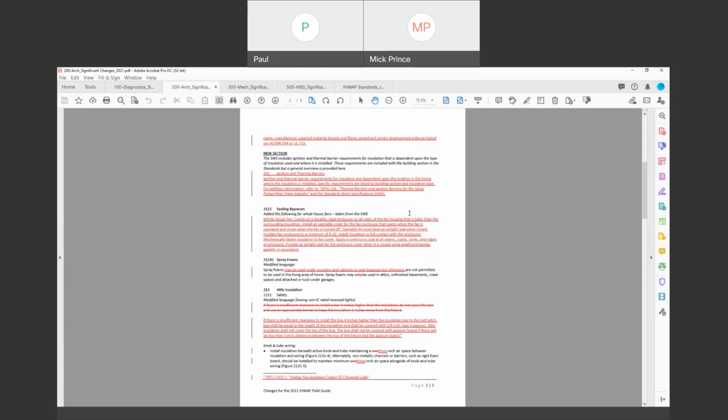Hey, Paul, why is the rim joist excluded from this? The code says you can get up to 3 inches of spray foam before it has to be covered with an ignition barrier. Okay. So in most cases, we're not going more than 2 inches, so that can definitely be exposed. And that's in a rim joist only, where you can have up to 3 inches. Yes, rim joist, basement or crawl space. That's correct. It's basically a de minimis area and thickness. Yeah. Right. Okay.